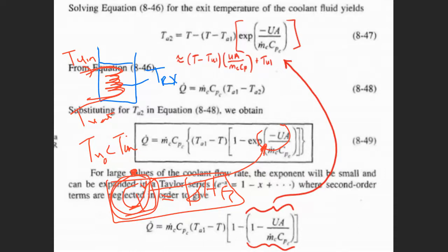So if I have heat transfer, of course, that Q has a heat transfer constant, the rate constant for heat transfer. I need area for heat transfer, so that will be the area of my coil. So I'll have an overall heat transfer constant, and then the driving force for heat transfer is the temperature difference between the stuff that exchanges heat with each other. That's what it boils down to.